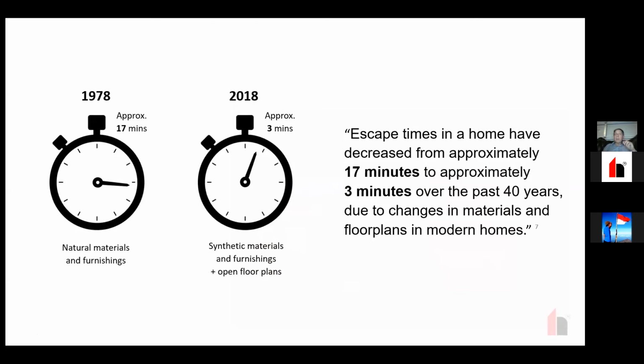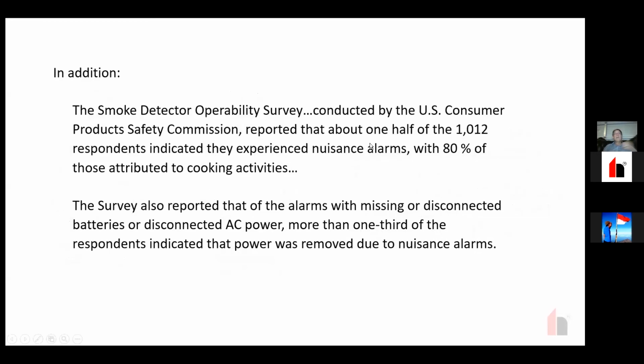But there's the second problem too, the second problem of unwanted alarms from cooking, you'll recall. There was a survey done, the Smoke Detector Operability Survey, conducted by the U.S. Consumer Product Safety Commission. They reported that about 1/2 of the 1,012 respondents had indicated that they had experienced nuisance alarms, with 80% of those attributed to cooking activities. The survey also reported that of the alarms with missing or disconnected batteries or disconnected AC power, more than 1/3 of the respondents indicated that power was removed due to nuisance alarms.